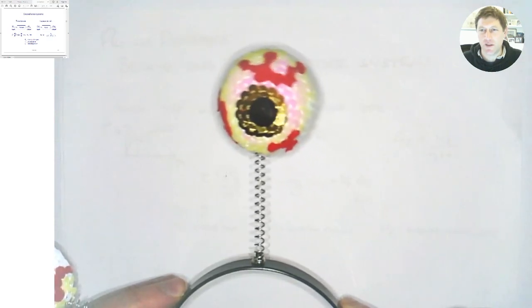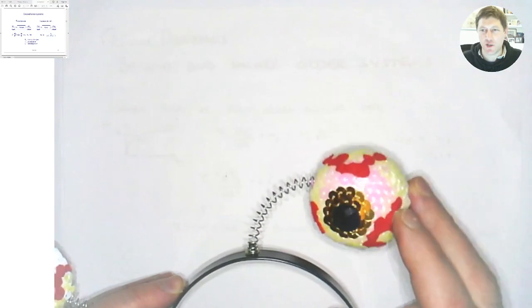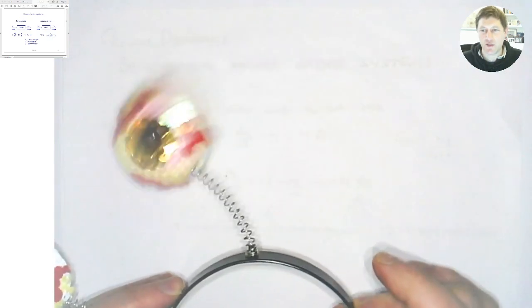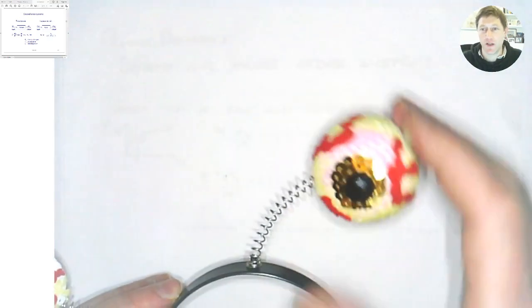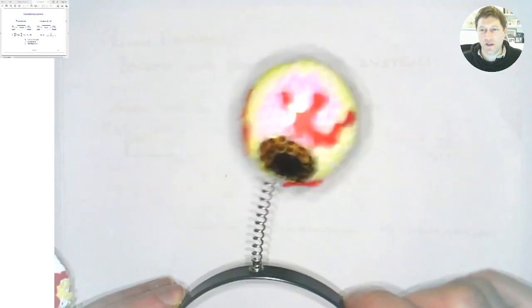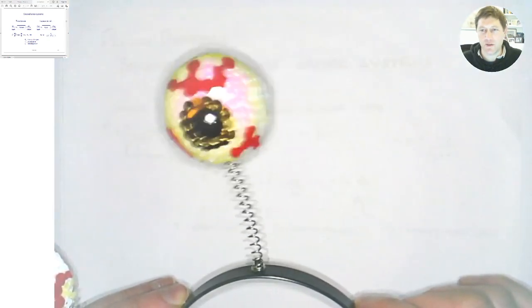If you look at it, give it a twang, it responds to a perturbation by oscillating, but then that decays and tends towards a steady state value. So this is a system that's got storage of energy in the spring, and then it's got dissipation of the energy as it moves, and the energy gets dissipated through the spring and through movement against the air. And this is a second order system. So you could try and analyze that to work out what's happening at a mechanical level, or you could just look at the response and learn something about the system by looking at the response to an input. So we'll look at that again a little later.